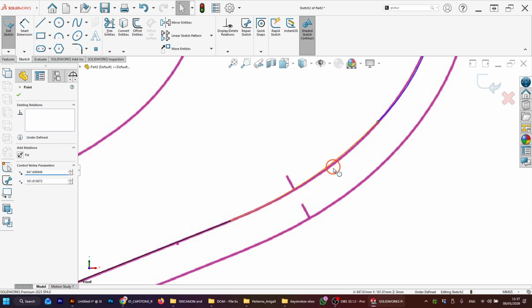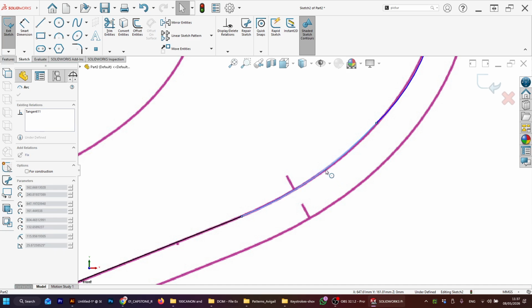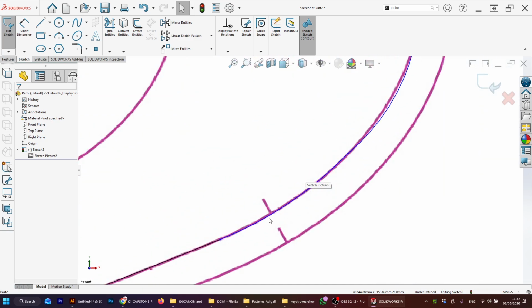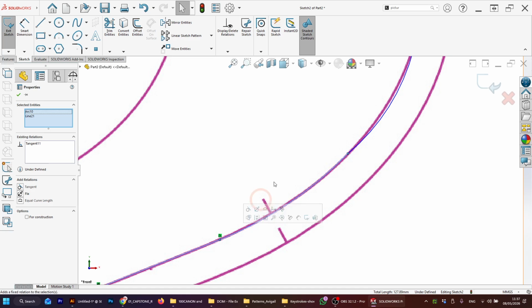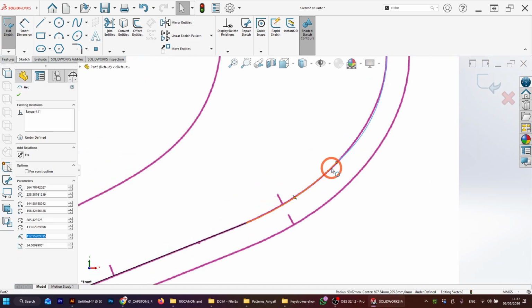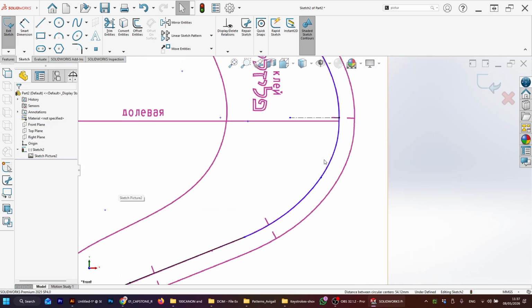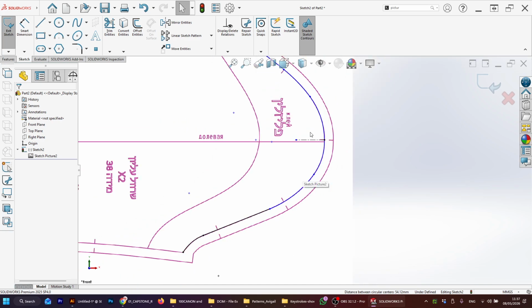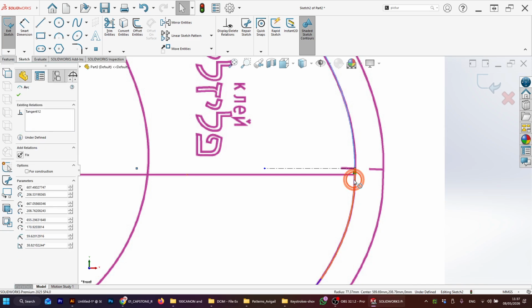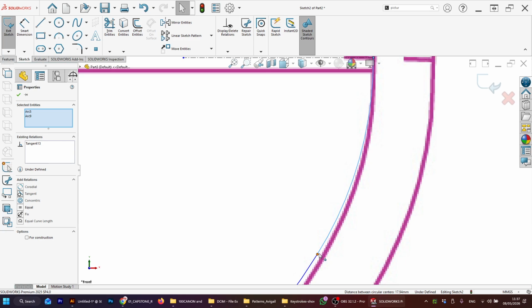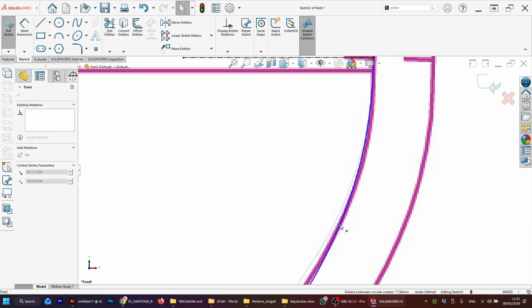Click, control, click, tangent. Now I can also start to place that point on the line and play with it. Take your time, because once you master 3-point line and 3-point arc sketches, and what we are doing now is a complete one, you're good. So this and this are already tangent. Now let's do tangent: click, click, curve, control, tangent. You can see that it naturally goes with the flow of the sketch at one point. Click, click, selection of two lines, control on the keyboard, tangent. Because if not, you're going to get a little spike.